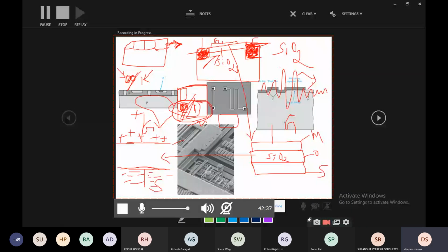Why is it converted into digital? To store that data, right? Once it is converted into digital, it is very easy to store that 0 and 1, that is digital data, and it is stored with the help of MOS capacitors, and these MOS capacitors are present in the RAM and ROM, right? So basically in RAM again we have DRAM, SRAM, all those things we will study in the upcoming semesters, static RAM, dynamic RAM, and all that I was saying, right?